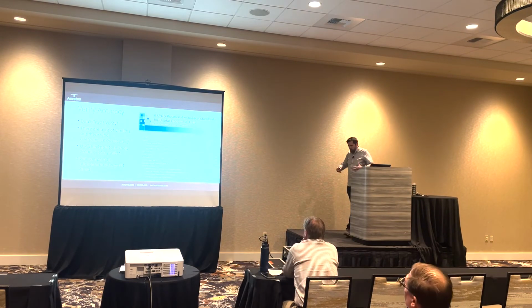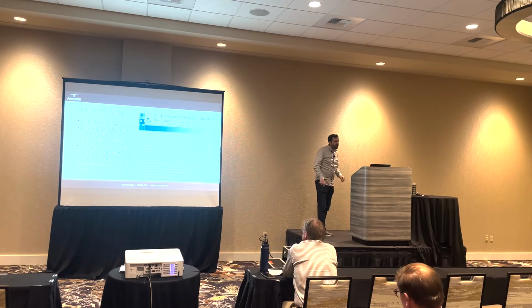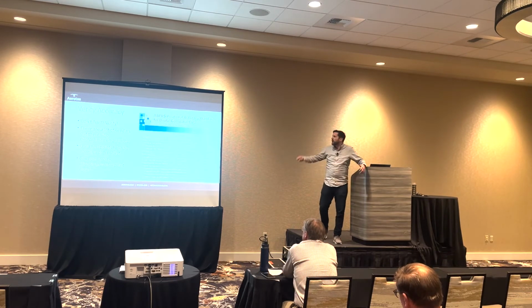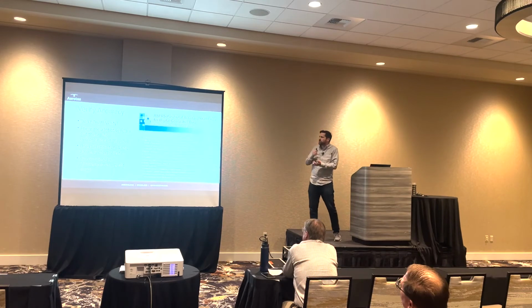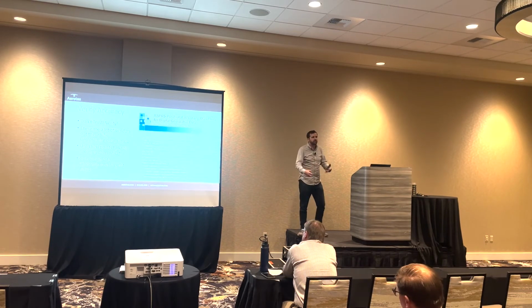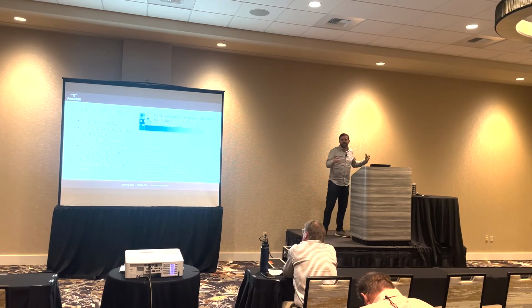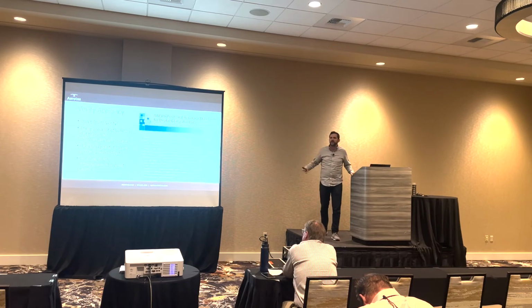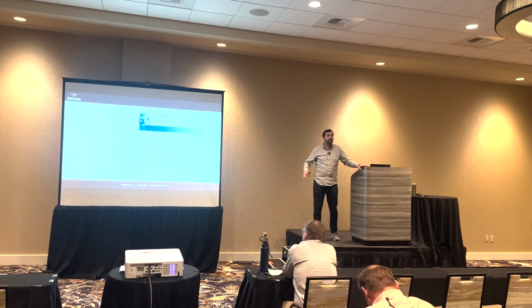And then also, early on in this process, before we even start vectorizing, classifying, anything like that, verify your accuracy. I mentioned this before. The ASPRS, that nonprofit organization, has published the ASPRS Positional Accuracy Standards for Geospatial Data, which is the academic backup for how you validate and prove the accuracy of your data. Again, this is part of what makes this wonderful, it's based off of decades of research. Aerial surveying has been around forever.